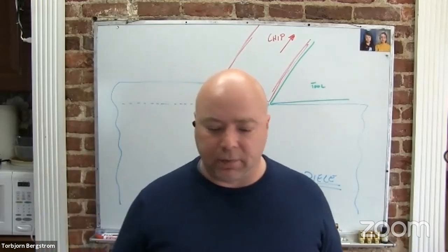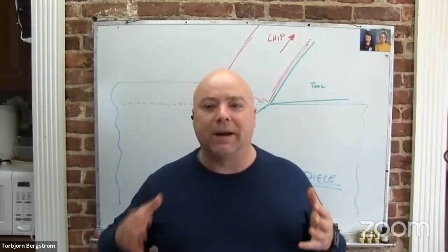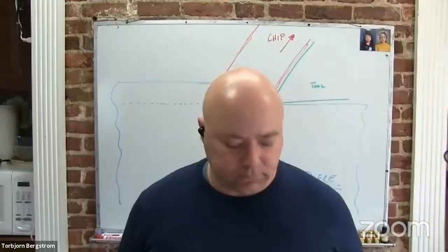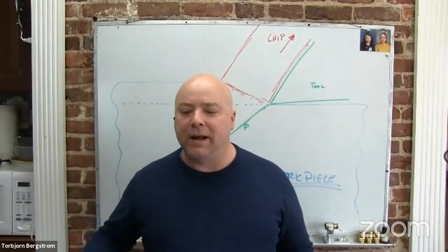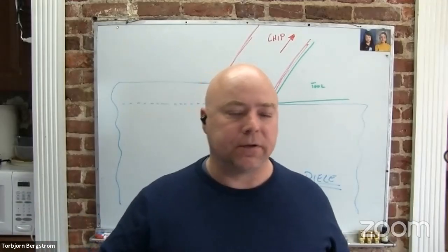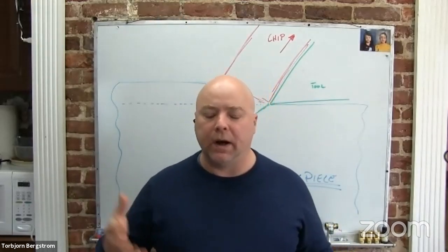Why else might we care about what the force is? Might determine how deep we can make a cut. So the deeper we make, so if I make a cut deeper, so if I increase my depth of cut, is the force going to go up or down? Up. If I increase my depth of cut, the force goes up every time if I don't change any other factors, right? What else would make the force go up every time if I don't change any other factors? Speed. Depending on the units you use for speed, either yes or no. But okay. What else makes the force go up no matter what I do?